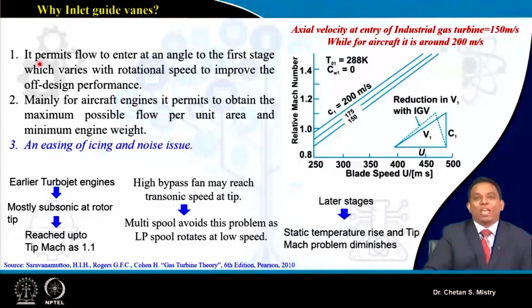So you can say that by incorporating these inlet guide vanes, you are enhancing your performance even in off design conditions. Okay, now it says this gives the maximum possible flow per unit area, and that gives the minimum engine weight.